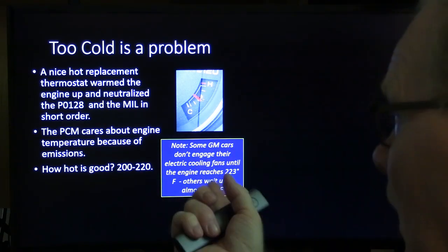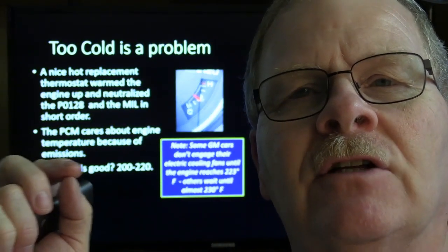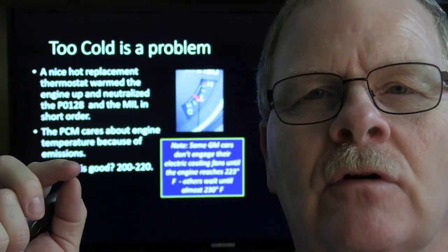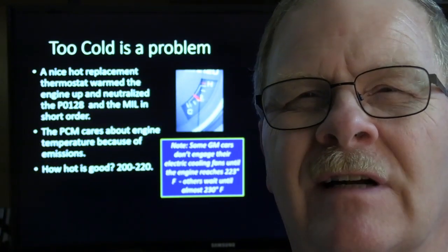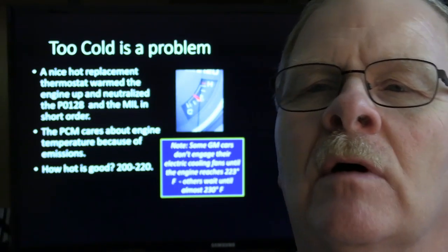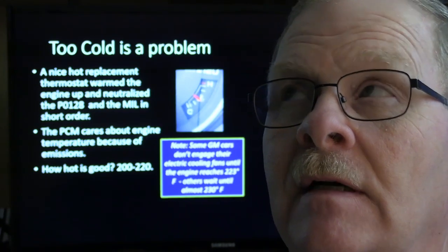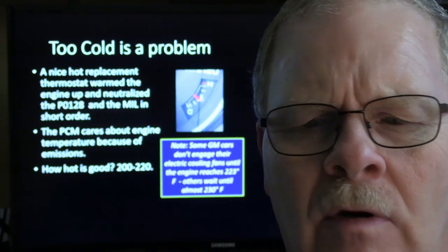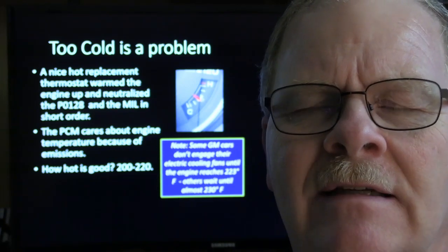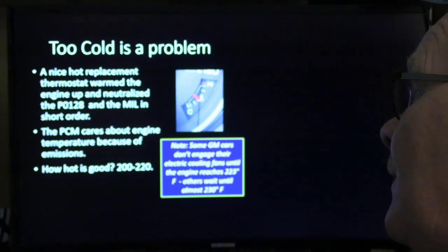But for good emissions and a healthy engine, it needs to run a little over 200 degrees. Matter of fact, if you look at some of your older Chevrolet Cavaliers, like a 97 or whatever, and some of them in the early 00s, they won't even turn on their fan. I ran into a couple of them that didn't turn on their fan until the coolant got to 228. So you've got to make sure that you understand that.